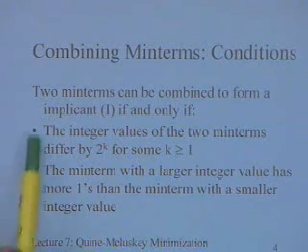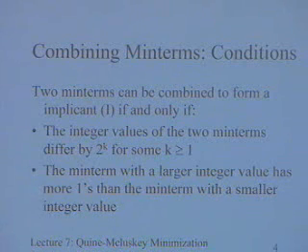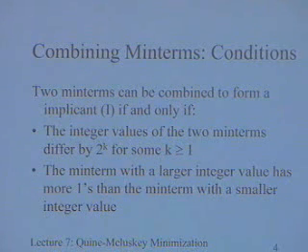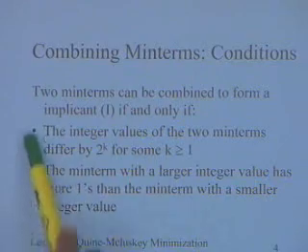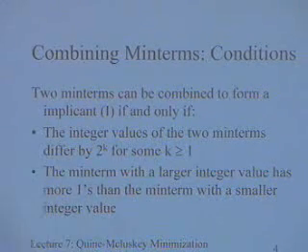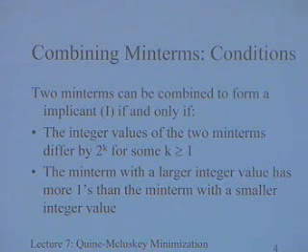Primarily what we are saying with this is, if you consider the 2 minterms, one of the variables has to be present in complement form in one minterm and true form in the other minterm. If you consider any variable which is present in complement form in one minterm and true form in the other minterm, this condition will be satisfied, because this particular variable has some weight, depending upon the number of variables.